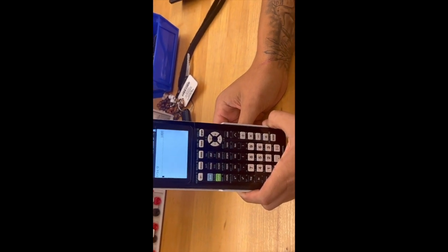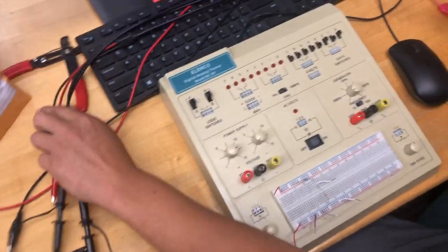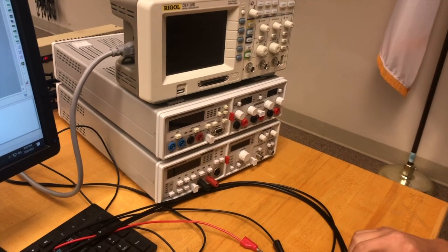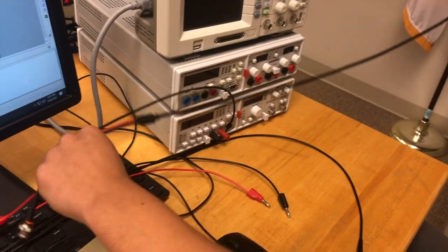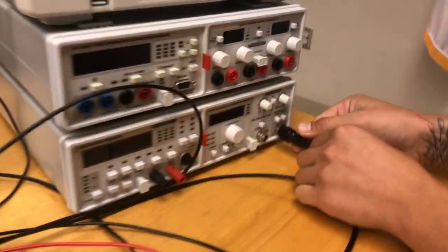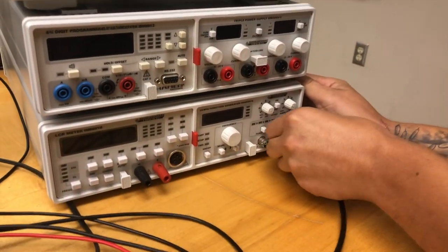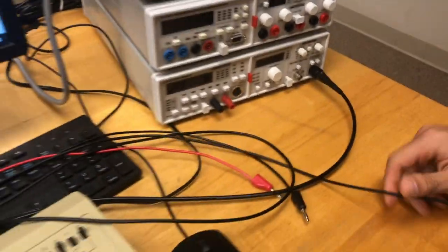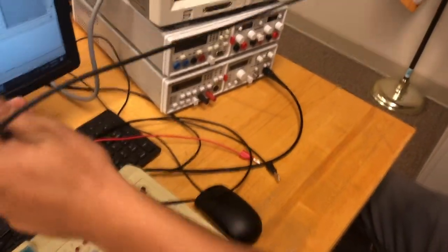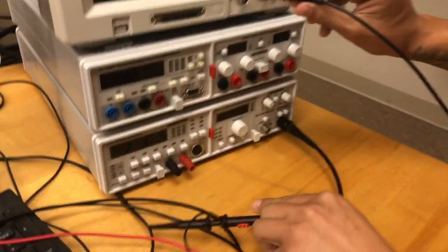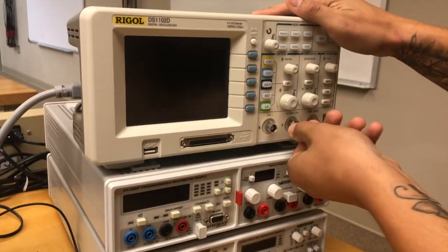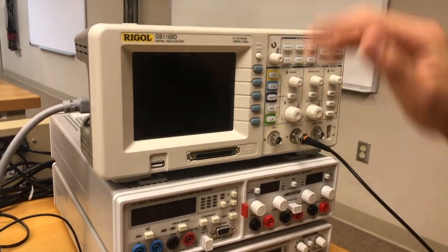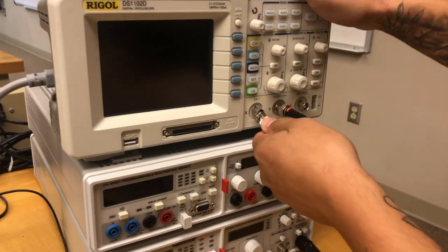1,000 hertz. Here we're going to be doing the bench portion using the multimeter, function generator, and the oscope. Here we will have the function generator cables. We'll just install right here on the 50 ohm output. Next, we will have the oscope leads. Put one on this second channel, and the next one will go on the first channel.